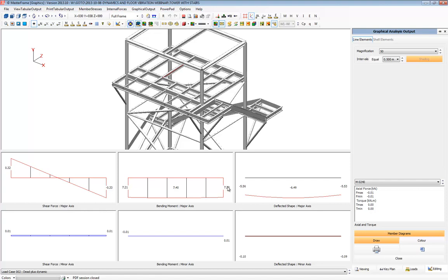So we think that this means these extra dynamic forces can really be accounted for here. And now you can carry on with this and design this beam to this load case, which has significantly higher bending moments than it did if they weren't accounted for.